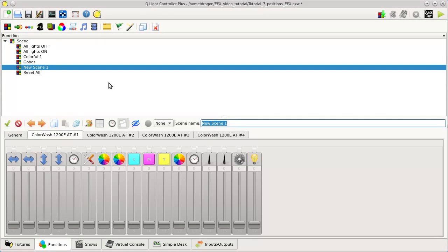But here's the problem: the DMX works by numbers, and numbers going from 0 to 255, while normally positions are expressed in degrees, so it is difficult to know exactly where you are pointing at, especially if, for example, the pan range of a fixture is 540 degrees, so more than one complete round.